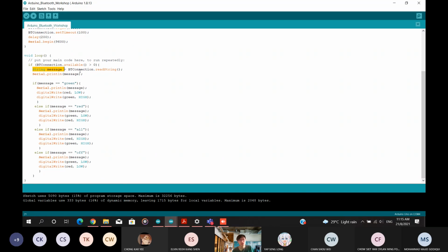And then I would want to set it as a string message. Normally we would use string because string is much more easier to send. If you want to send by bytes, you could, but it will be much more harder because it is a rather asynchronous type of message. So you would actually depend heavily on timing. And if you mess up the timing, your message that you receive is going to be very weird.